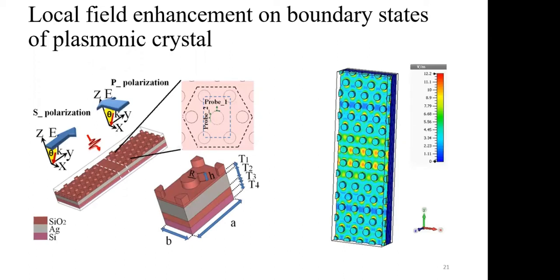Another design which we finished, and it was interesting for us, worked with p-polarization for a plasmonic crystal, which we measured for both modes, each unit cell as a honeycomb that you can see. Two probes are installed here. We tried to design it to work as an edge state plasmonic crystal, and we wanted to direct the electric field in the middle.